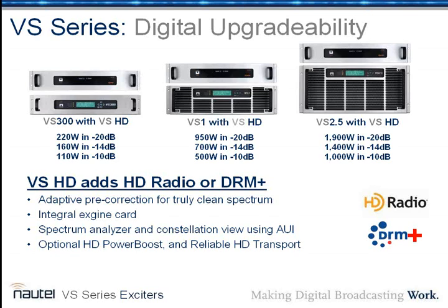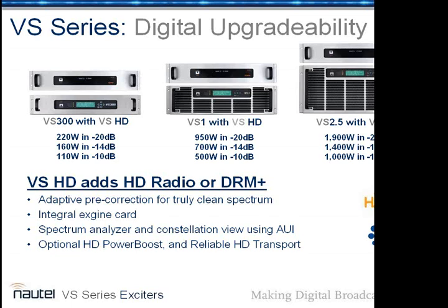And if you get the VS HD, all these VS transmitters are capable of doing HD, so it is possible for you to actually use it as an HD exciter. You can go a step further than that. In a situation where you needed it as a higher power backup, you could run it in HD to drive the main, and then switch it to analog only for backup on another preset. That's right.